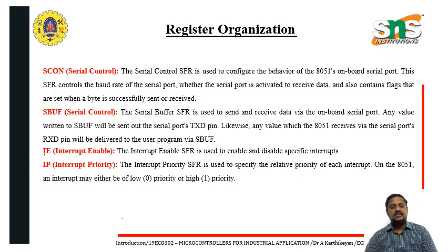And SCON, the serial control register, is the SFR used to configure the behavior of the 8051's onboard serial port. This SFR controls the baud rate, whether the serial port is activated to receive data, and contains flags that are set when a byte has been successfully sent or received.